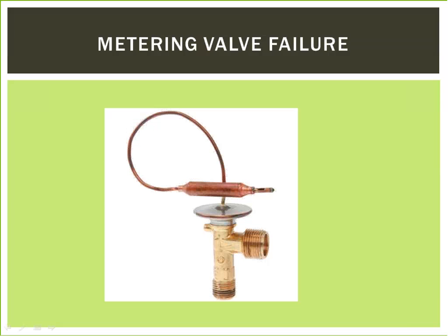A low side restriction will always result in excessively low pressures. High side restrictions will generally lead to excessively high pressures. Contamination is repaired by performing system flushing and relubrication, as well as replacement of filters and possibly the replacement of the metering valve.